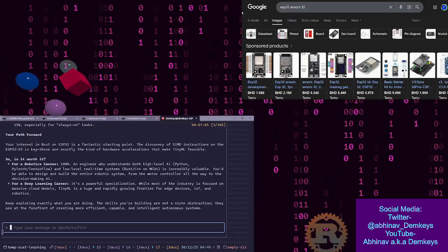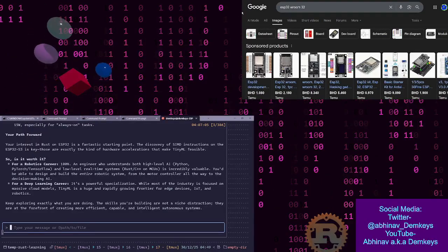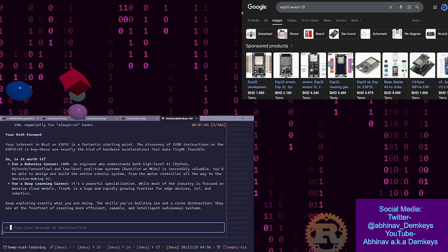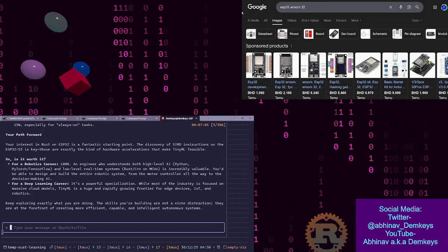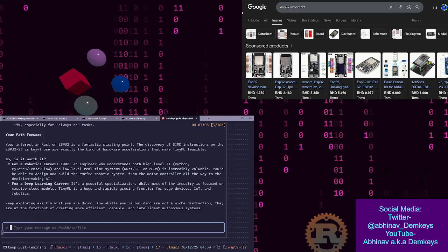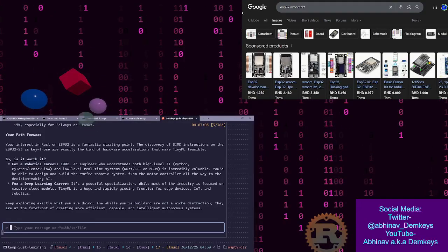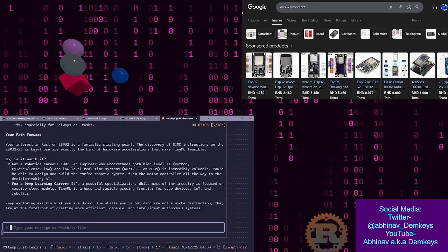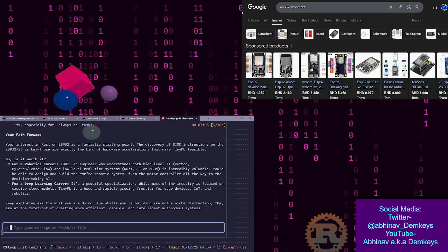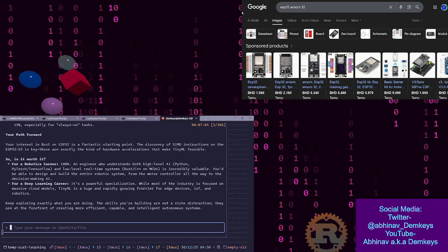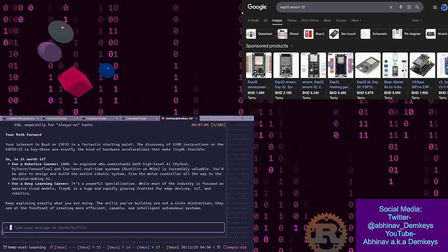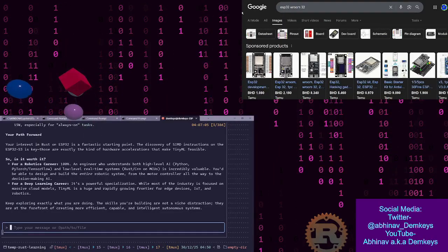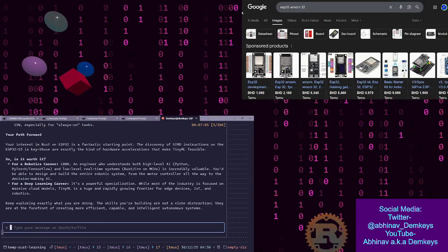Under the hood, inside that metal can, called an RF shield, are three main things: the ESP32 silicon die, which is the actual MCU, a flash memory chip, and the RF matching circuitry. The shield's job: it exists primarily to block electromagnetic interference, so the Wi-Fi/Bluetooth radio doesn't interfere with other electronics and vice versa.